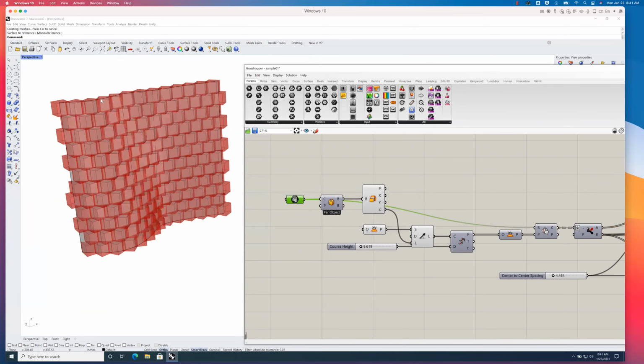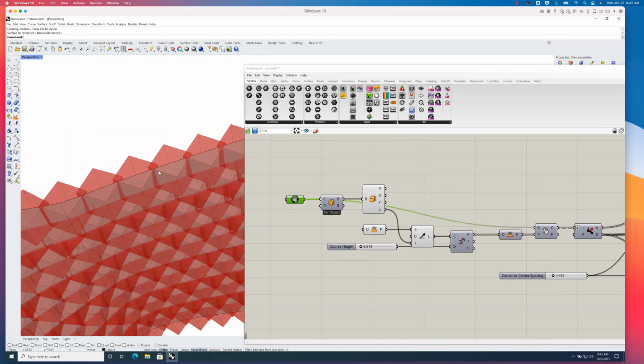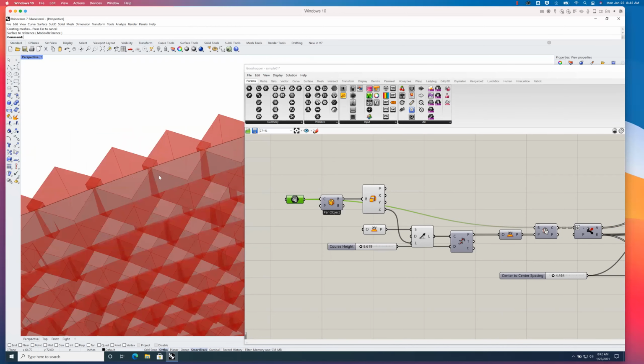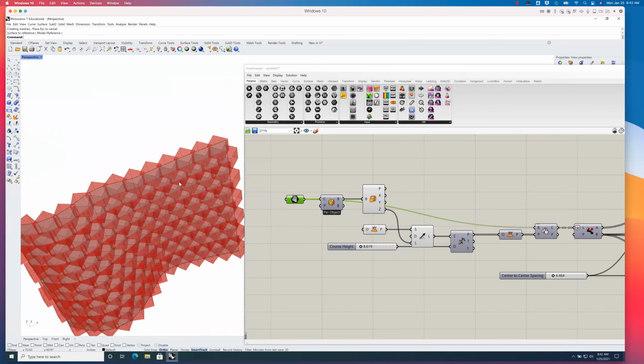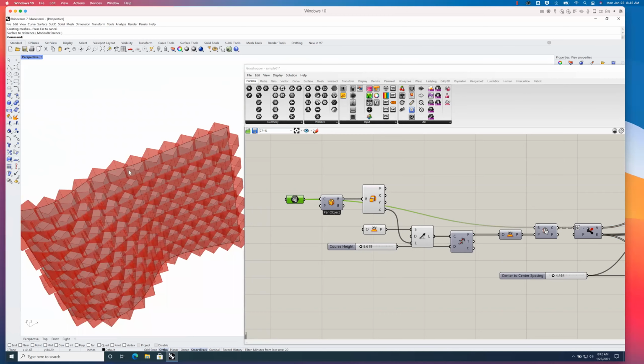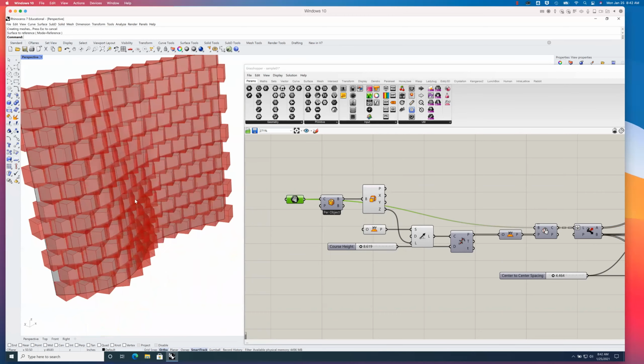So here I'm going to reference that surface in, and now you can see it started to populate with masonry blocks, let's say, that are 8 by 8. Of course, we have some problems going on here. We either need to have our masons get out the chop saw, or we need to adjust some parameters in order to prevent these collisions in between each unit.